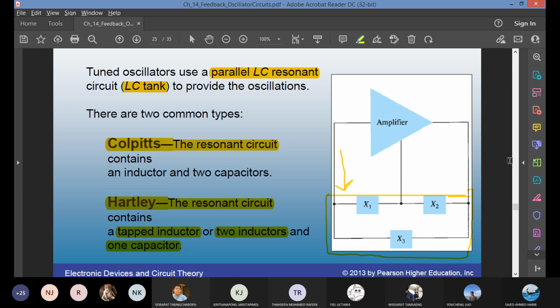However, if you pair a Class C power amplifier with an LC tank and make the Class C amplifier frequency the same as the resonant frequency of the LC tank, in that case you will have a 360-degree full cycle output. That's the only way you can have a Class C conduct for the entire cycle. Class C is used mostly in radio communication circuits, and the LC tank circuit is also a common application in radio communications.